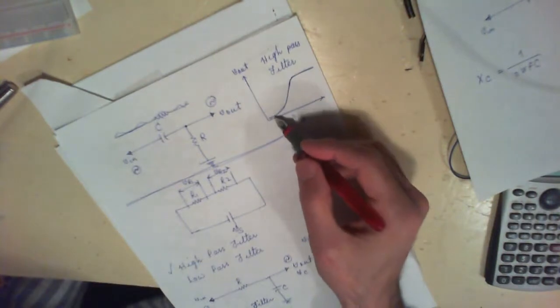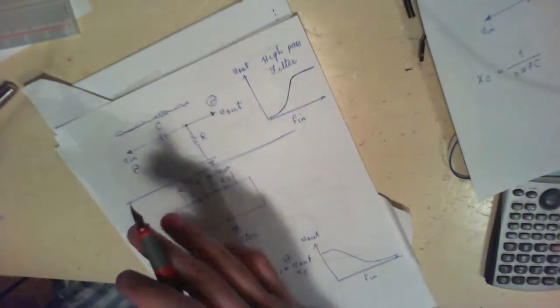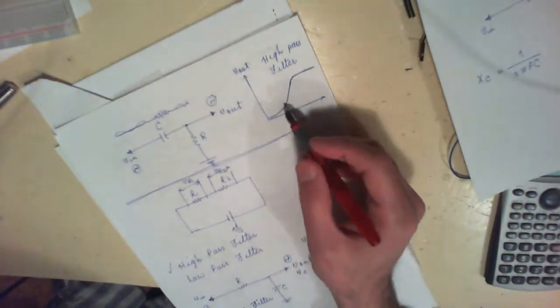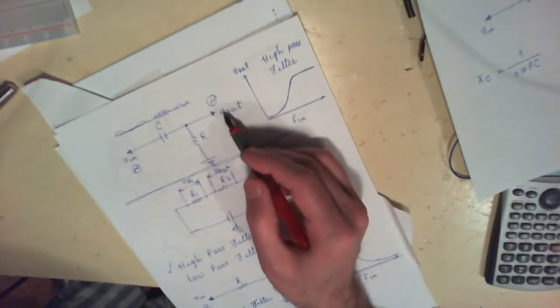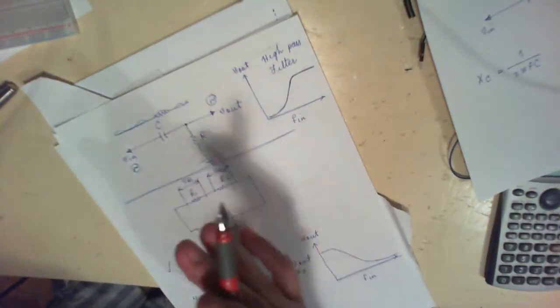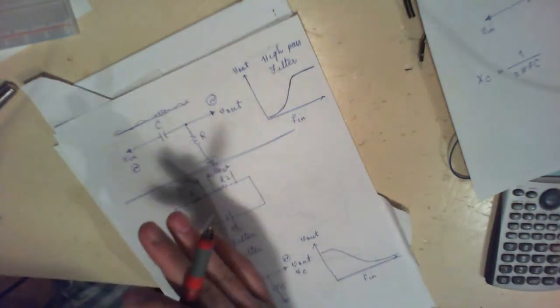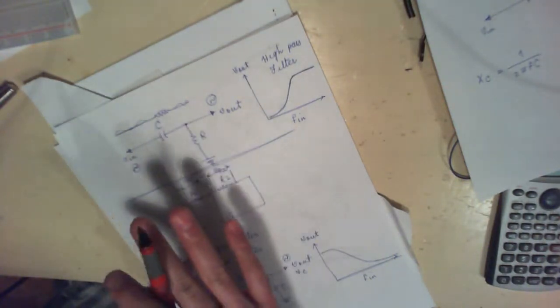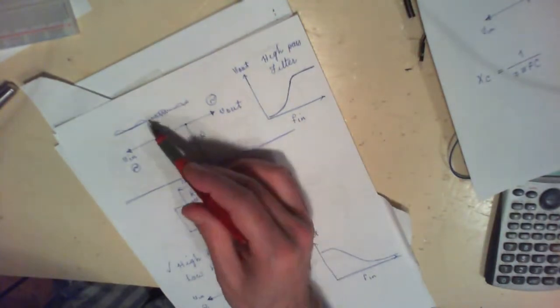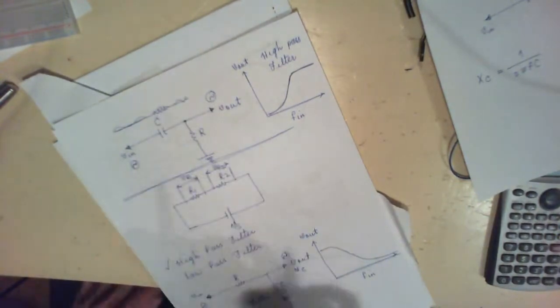But what happens if you actually try to do this, for example, using a signal generator and a few capacitors and some resistors, what you will find out is that this output voltage is going to lead this input voltage by different values, depending on your frequency, and depending on the value of this resistor, and depending on the value of this capacitor. That is what I wanted to show you in this video.